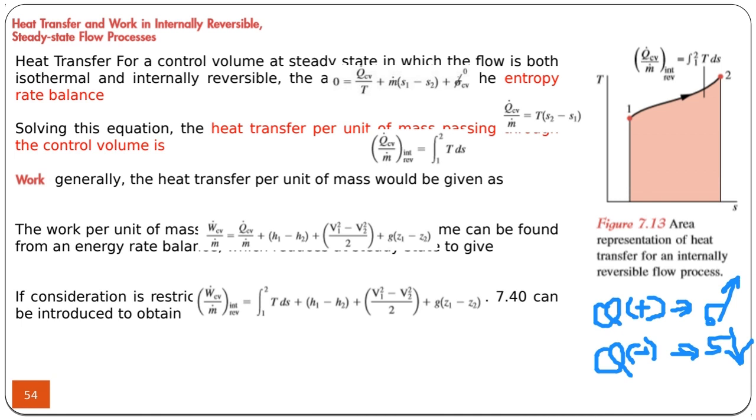So we can write the entropy balance equation for a steady state system as this. If it's a steady reversible system, the entropy production will be zero, so that the entropy change due to the heat addition will be only this. This is for a reversible system, where sigma is zero. So we can calculate the Q from the change of the entropy.